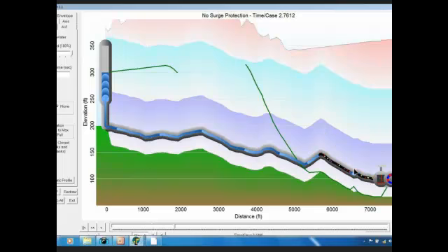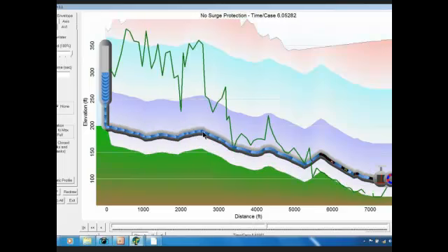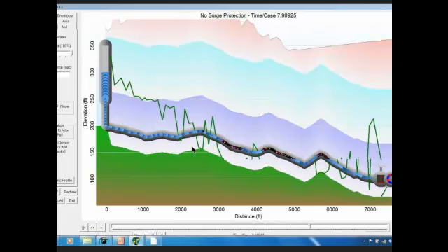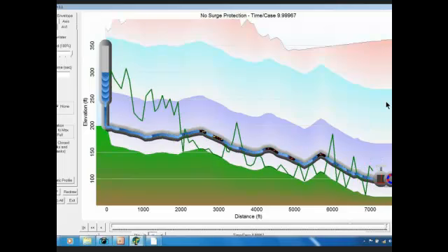Now here, check valve closes. This is cavitation, feeding cavitation. If you watch, when the cavity collapses, you get pressure spikes. Not a good situation, but very common. So in this particular problem, we had no surge protection. We got lots of cavitation. This could be acceptable in some, like a dirty water pipeline, raw water or something, if the pipes could withstand the full cavitation.